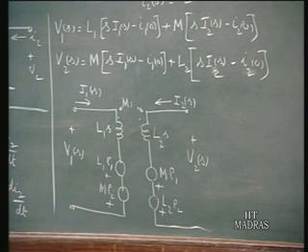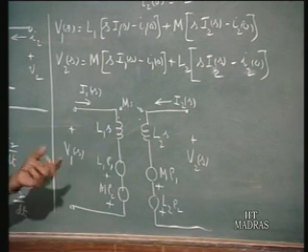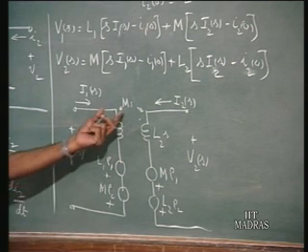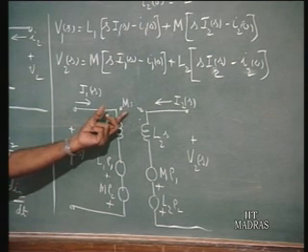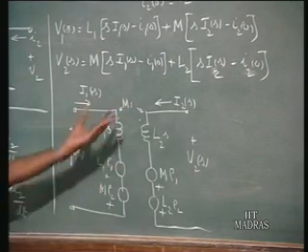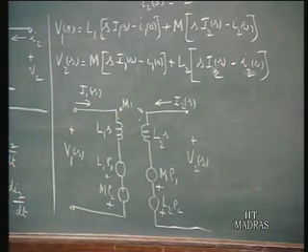This is very similar to what you do in the case of steady state circuit analysis, AC circuit analysis, where the self inductance is represented as an impedance j omega L1. The mutual impedance is j omega M. So, instead of j omega we have S, otherwise it is exactly the same situation that you have in the case of AC circuits.